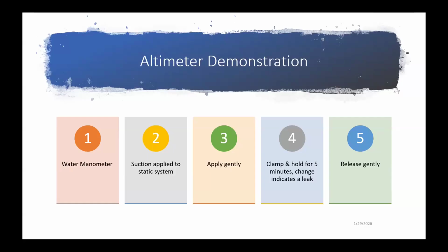especially if you've got an older glider that's got the vinyl tubing in it. You need to check it periodically because that vinyl will harden over time, and when it hardens, you can get leaks. The one thing you want to be careful of is if your altimeter is mounted to a moving part of the glider, for instance, if the instrument panel lifts, you need to be careful when you're raising and lowering your canopy.